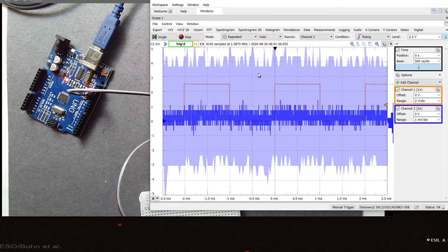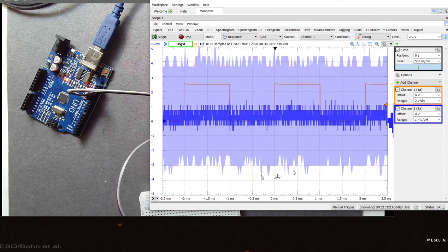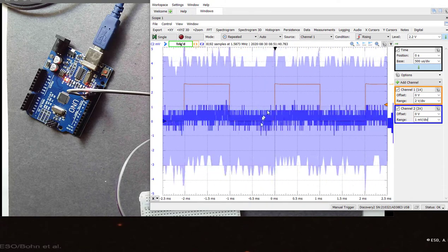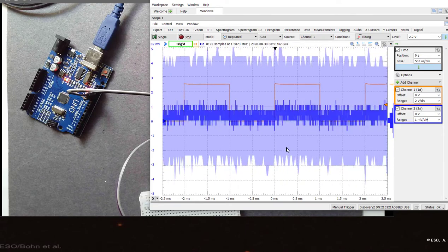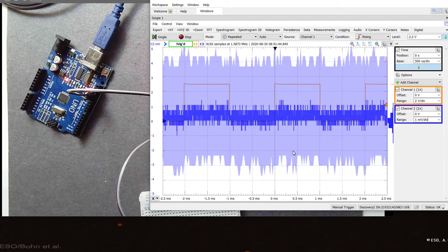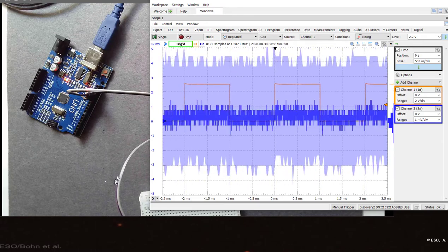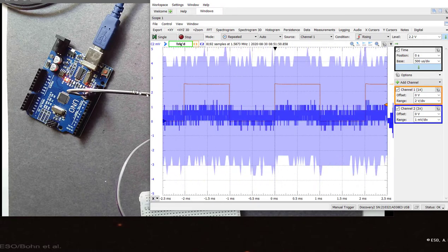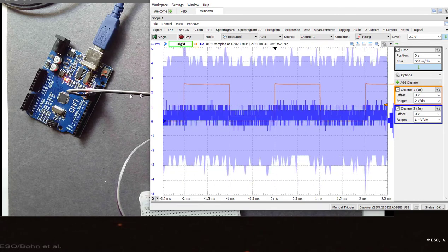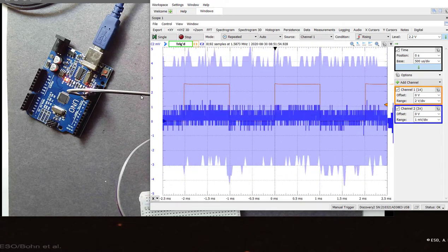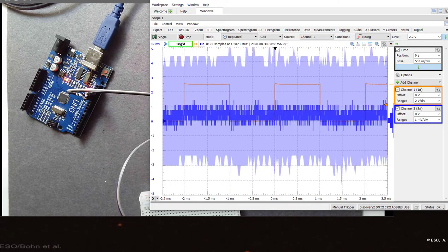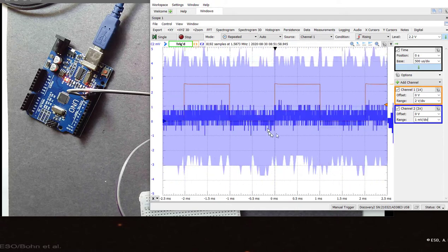And you can see that, gosh, there's a lot of random high frequency noise. This is the lower frequency. And remember, if it's magnetic field coupling, what is the only thing that changes the magnetic fields inside this loop? It's changing magnetic fields from this loop. And what is the only thing that causes changing magnetic fields? It's changing current. And that's what's going to happen on this edge.